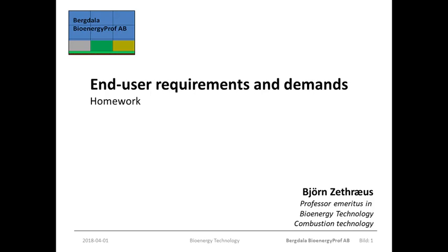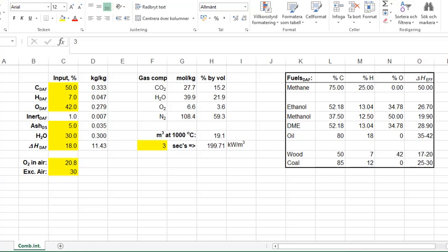One important characteristic for a fuel is the attainable combustion intensity. The combustion intensity will, together with the thermal insulation and any eventual heat transfer surfaces inside the combustion chamber, determine the real process temperature. You should make yourself a simple combustion intensity calculator. You can do that using Excel or any other spreadsheet program, or you can do it using programming aids like MATLAB or Scilab or whatever you want.